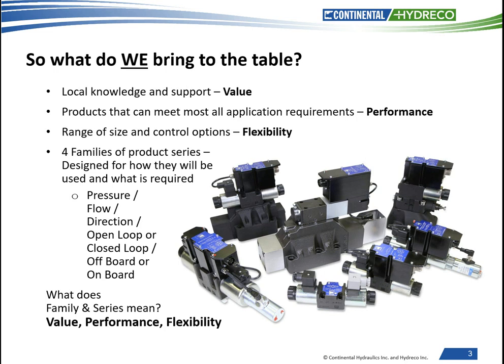Example, in normal hydraulics, pressure drops are typically designed out and are not desired. Conversely, in a proportional hydraulic circuit, pressure drops are incorporated to give the hydraulic stiffness we need for control. More and better filtration, and cooling may be required. Response times of the system also become very critical in meeting flow and pressure requirements. You may need to add an accumulator, as the pump response time may take longer than the time available to make the complete requested move.